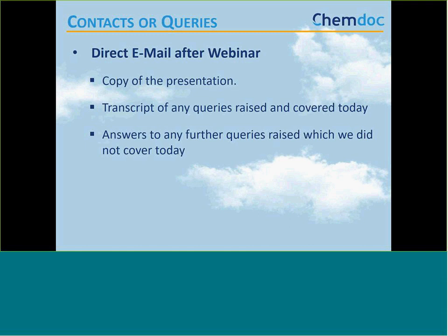The last question that was sent in was whether you should make different COSHH assessments for different departments for the same chemical. That is a definite yes. If the chemical is being used in the exact same way in a number of departments, we would say each department should write its own COSHH assessment, if only to take ownership of it in that department. But also, even though you may believe it's used in the same way, there may be different environments.